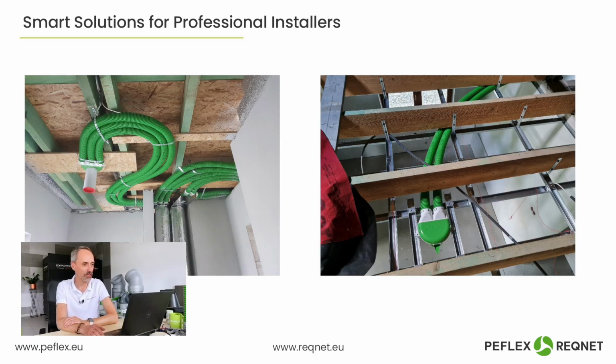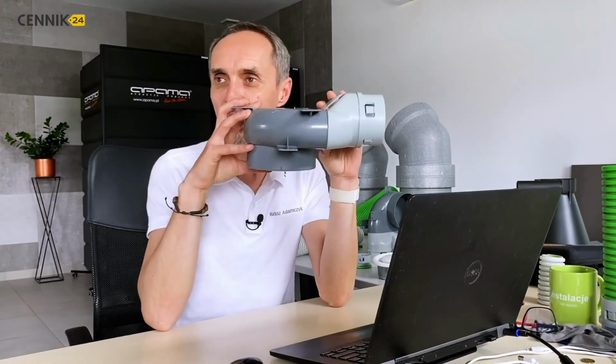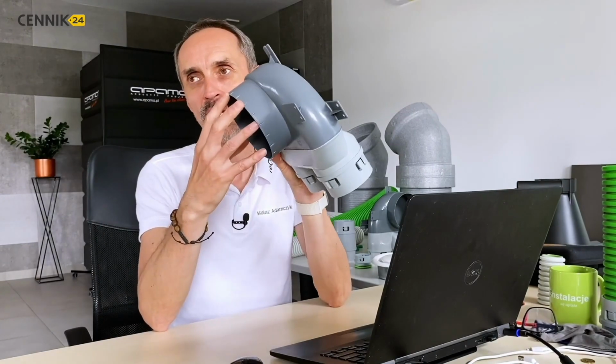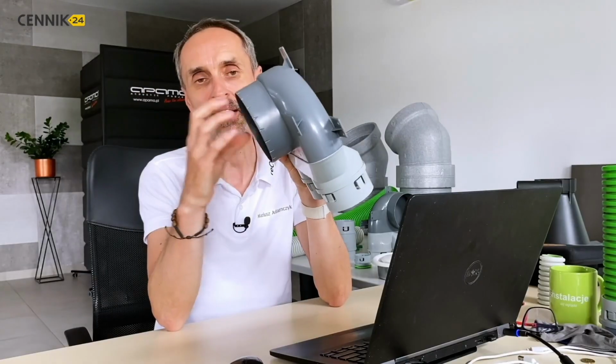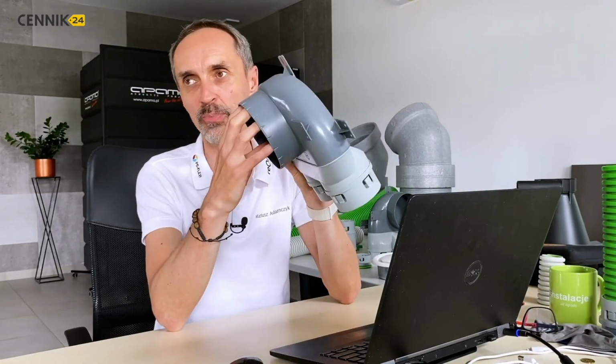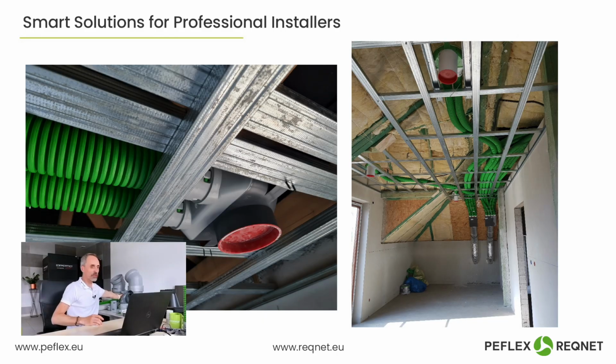Examples and possibilities include how you can run the system in the space of a suspended ceiling using extension pieces for plenum boxes, or, for instance, you could install a floor box. This might sound odd as a ceiling solution, but with an inlet for the spigot under the air diffuser, using a socket spigot, where the frame spigot of the air diffuser fits into the socket of the spigot of the plenum box. But that's in a solution like the one we have shown here, where the box is mounted to the structure, to the frame of the suspended ceiling.